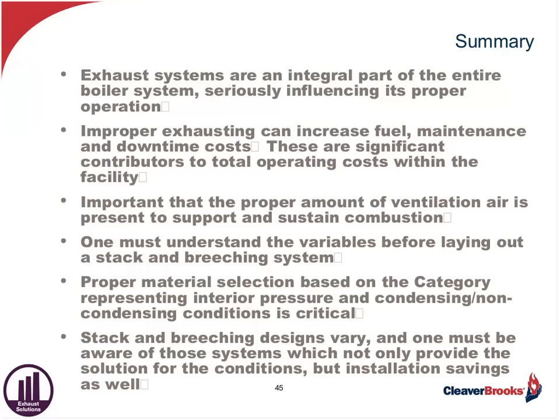We've selected aluminized steel as kind of a standard. Mostly it's a cost issue, but we've provided aluminized steel on the interior section of the stack and stainless steel on the outer, the exterior that's exposed to the atmosphere.